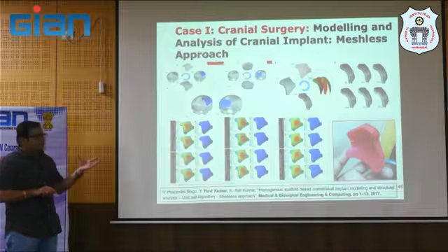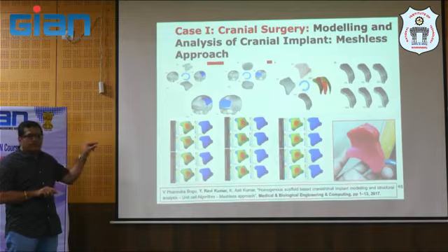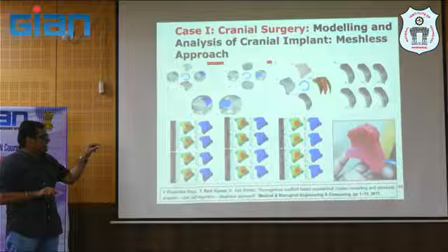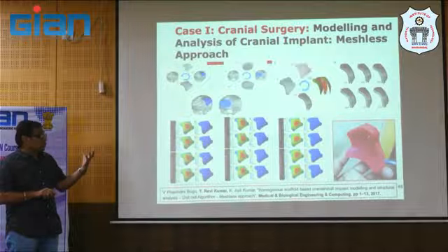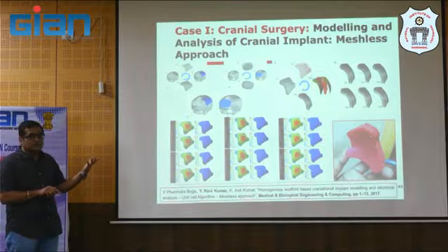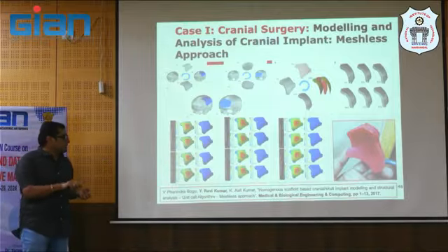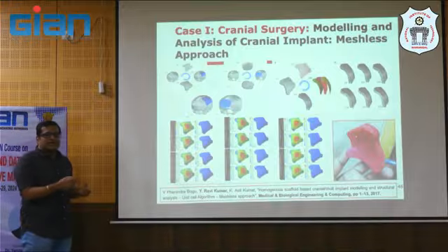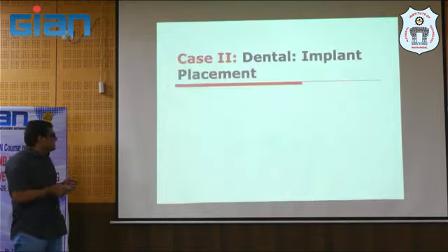And finally, you design and fabricate, but here you see it is a kind of sandwich structure, your skull, right? So the inner thickness of the skull is around 0.8, 0.9, and the outer is 0.4, 0.5, and in between you have a porous structure. So there is no other way than 3D printing to make it in a single setup, right? It is impossible otherwise, right? And it is patient specific. So you can very well adjust this porosity as per the patient requirement, the personalized implant which you can design, right?